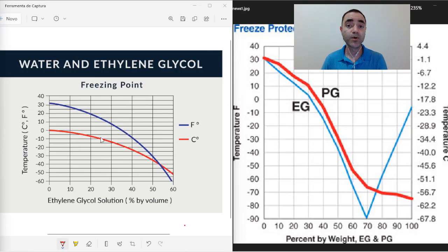But if I am operating at minus 10 Celsius degree, this is my normal operating point, and I can have deviations for this process. I don't know how much the chiller machine is able to achieve if I have low flow, for instance, or if I have a disturbance in my process. So as a chemical process engineer working with plant design, you must always think about the safety margin for the process.